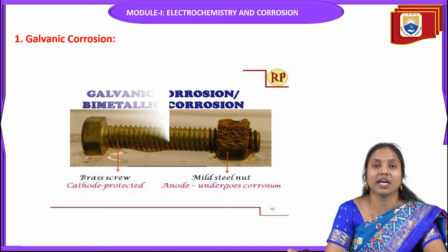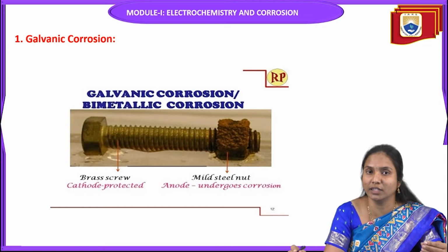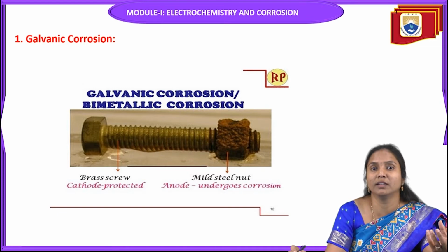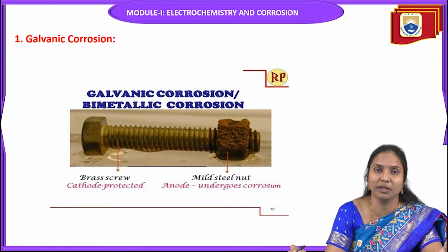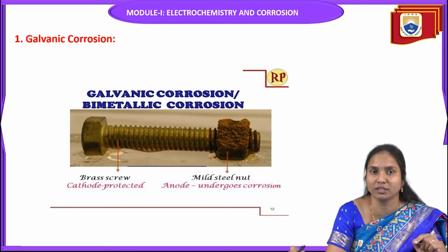Now let's discuss types of wet corrosion. Wet corrosion generally takes place when the metal is in contact with a conducting solution, or partially or completely dipped in conducting solution. In wet corrosion, electrons are liberated at the anodic area. Those electrons are consumed by the cathode in two different ways, evolution of hydrogen and absorption of oxygen. We discussed that just now.